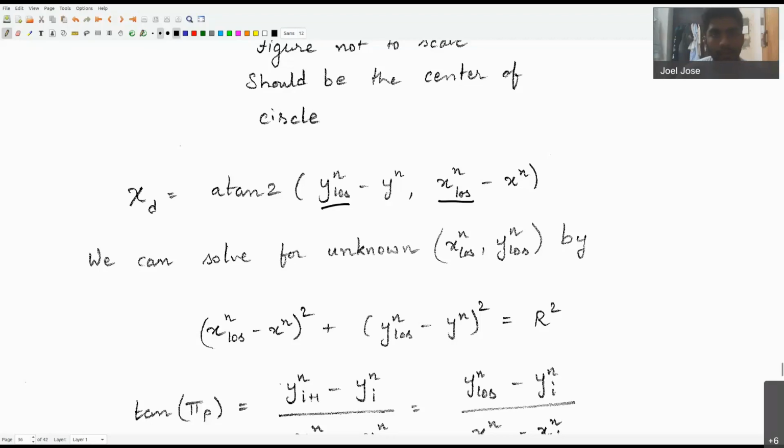And therefore you're already seeing that there is a downside. There is a point where we may be in trouble, especially if we choose an R such that R is less than the magnitude of the cross-track error. This method will not work. We'll necessarily have to update our R value in order to get a proper line of sight guidance.